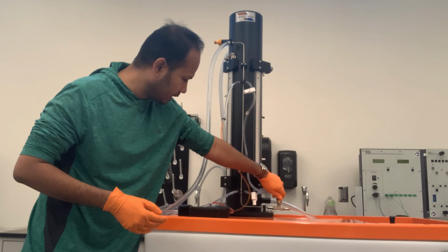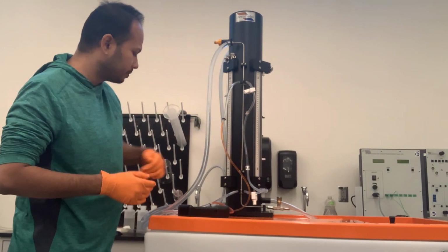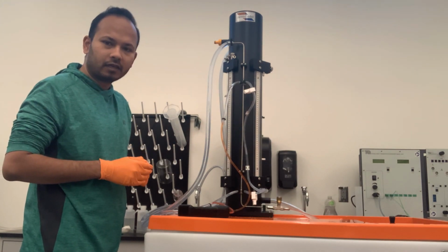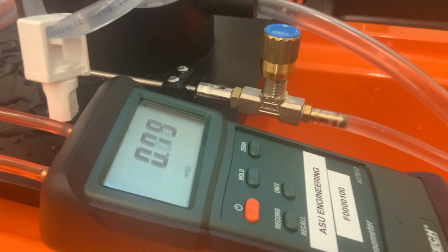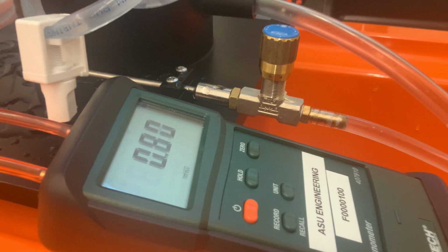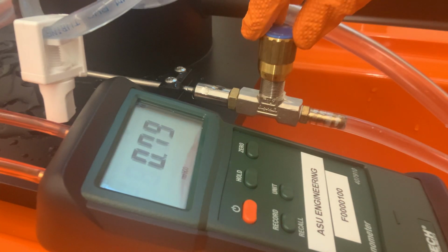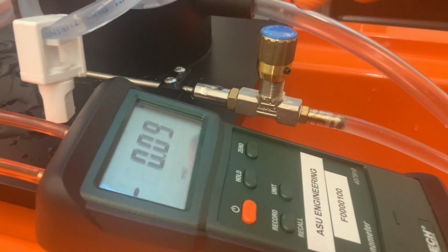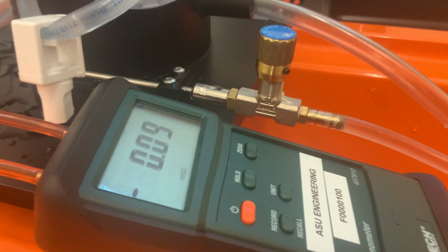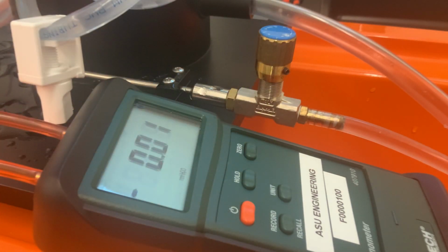Now I'm going to open the valve. And there is water flowing. And we can get the head loss. Again, to show you, the pump is running, the water is flowing through the pipe. What I have to do is close the flow. So there is no flow in the pipe. At this position, there is no water flow, and I have to tare, so make this one a 0.